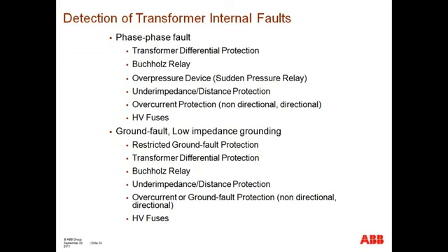So it's also known as a flow type relay because it essentially monitors the flow of the oil inside of a transformer. It provides, to a certain extent, good sensitivity, since when any type of electrical fault occurs, there's going to be this breakdown of oil. So this is not an electrical or a microprocessor device. This is a mechanical device that's built in as part of the construction of the transformer.